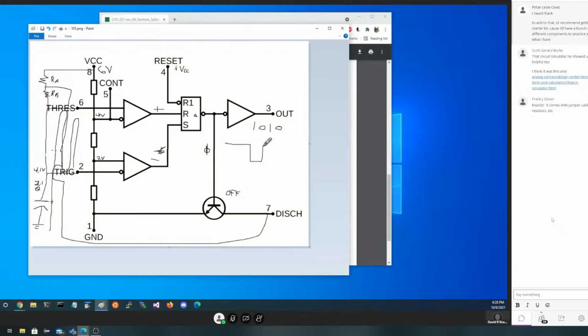But in this case, what we could imagine is this is on, this is off, this is on. During the time that it's on, it's going to be charging. The time it's off, it's going to be discharging. Charging. Externally, we don't see those signals anywhere that's going to matter because we're going to see it as though it's a rectangular wave. It's not square because the periods are different.